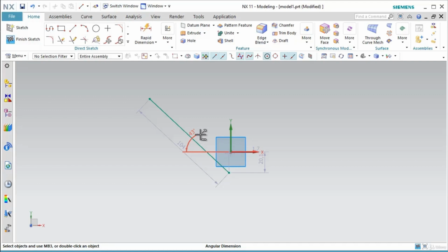Geometrical constraints are something like concentricity, parallelism, perpendicularity, vertical, horizontal, point on a curve, and any such relation that you are going to give between two entities. Dimensional constraints, on the other hand, are something like radius, diameter, distance between two lines, distance between a point and a line, and so many things where the measurement is a factor.